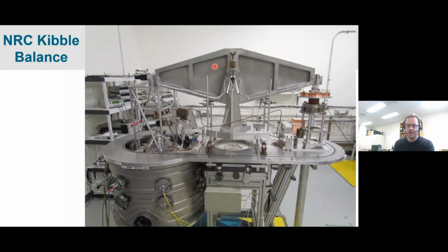And of course, you can see the pivots here, the equal arm with the pivots, which is boron nitride flat underneath a tungsten carbide knife edge. And here is the coil that we use to drive it during the velocity phases. And this all operates in vacuum. So here it's exposed to air, but we have a lid that goes down and it all runs under vacuum. And vacuum is critical to get to the low uncertainties that you need because it gets rid of buoyancy corrections.